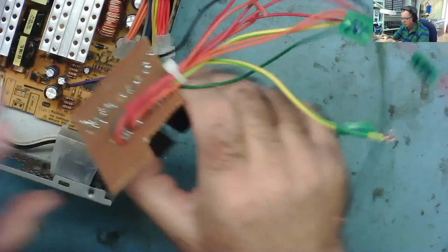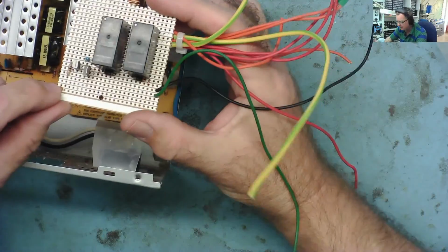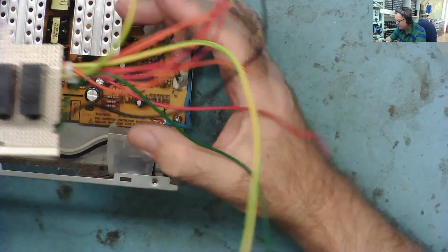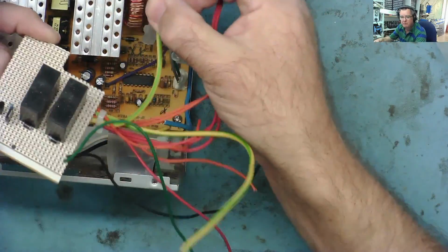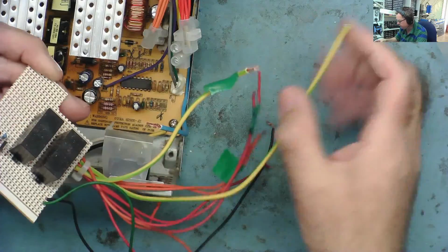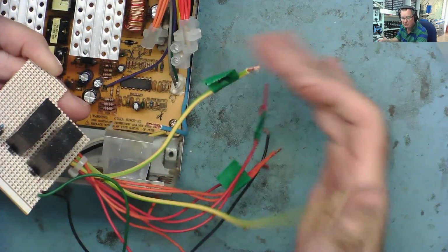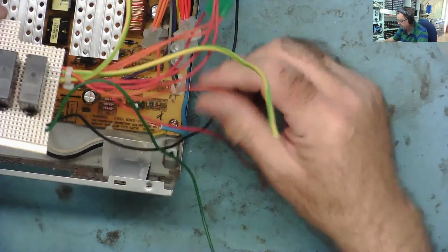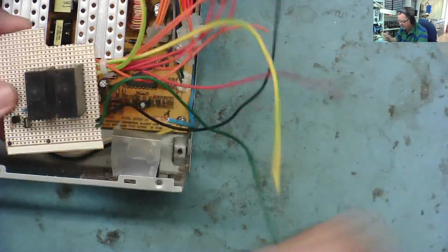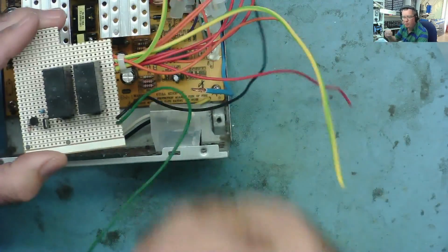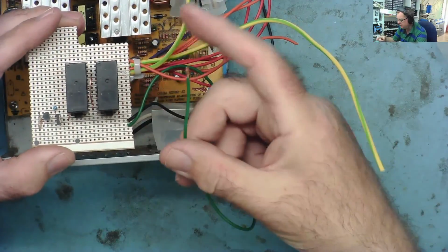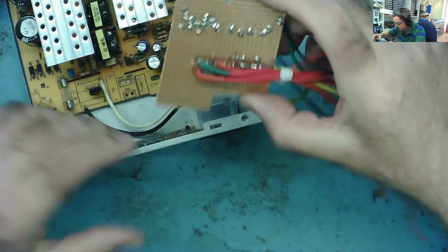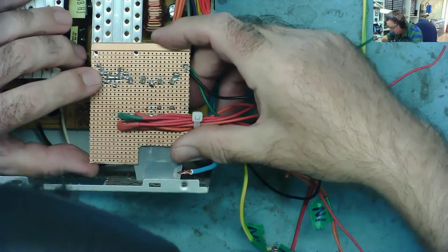This is my little circuit that I had on the breadboard. I've now wired it up on Vero board. I've tested this, so I've marked these. The yellow and green, but we'll call them yellow, that's your 12 volts in and out, and the same for the other ones, the orange and the red, in and out. So I've connected them all up, and I've tested this on the bench. So the green wire, when I ground this, the relay closes, so I know it works. I've drilled a couple of holes in the back of it, and I'm going to mount this onto the top of the heatsink here.